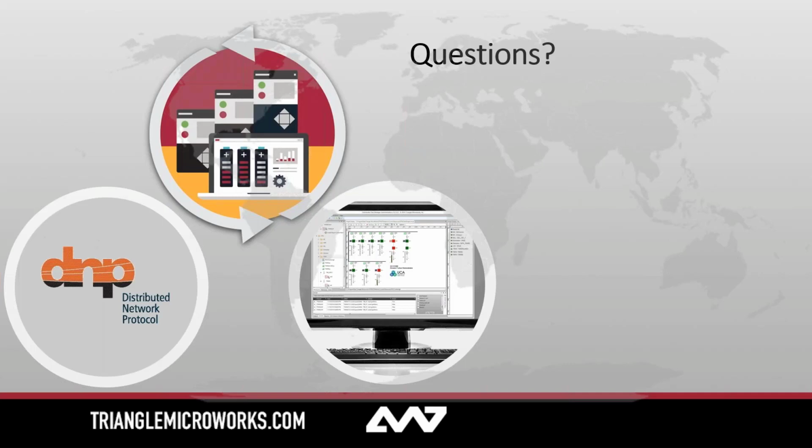For example, if you're in a physical substation and you have a GOOSE server, you have a 61850 server running, and you accidentally flip a bit and tell it to send a GOOSE message out to open a breaker, like I said, the network doesn't know that's simulated unless you set the test or sim bit or things like that. And you could actually have breakers open or responses in your physical system that you didn't really expect. So again, DTM is kind of a test tool, but it could be used as that. Just be very careful.